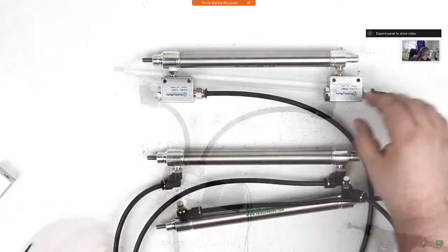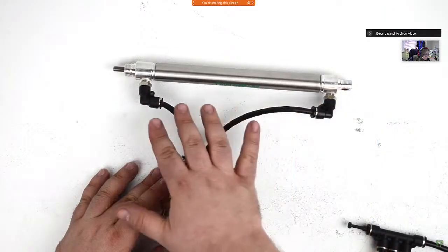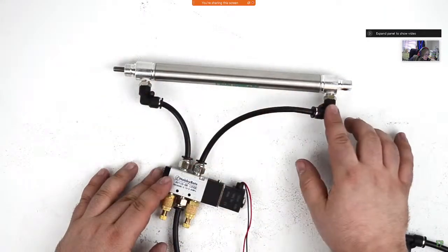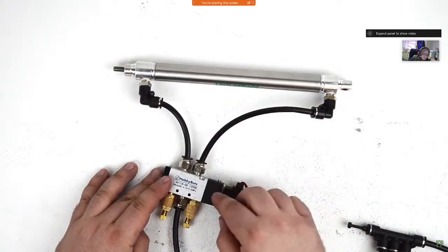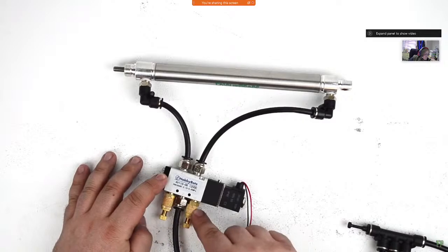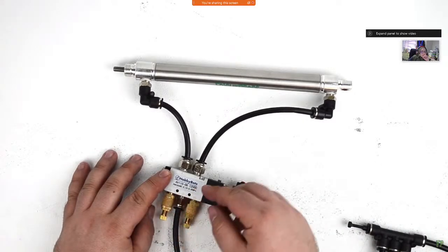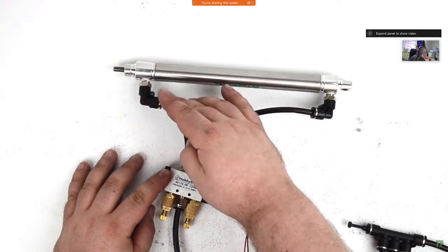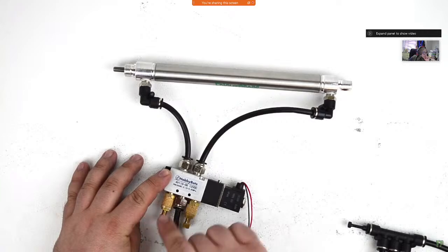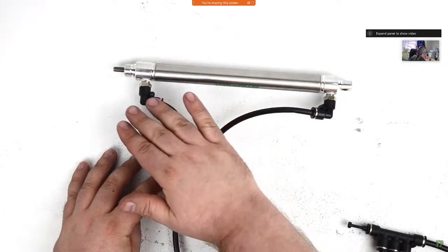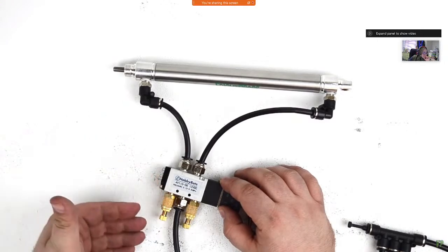This is much more difficult to do without quick exhaust valves. Another way to control the speed of a cylinder is that, rather than adjusting the flow of air at the cylinder ports themselves with flow control fittings here, you can control the flow of air at the solenoid exhaust ports here. This works by restricting the flow of air as it passes back from the cylinder out the exhaust of the solenoid. You can meter it here rather than metering it as it comes into the solenoid. They both accomplish the same effect, just at different places.